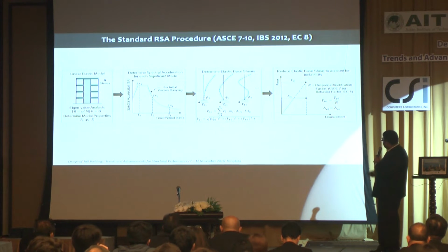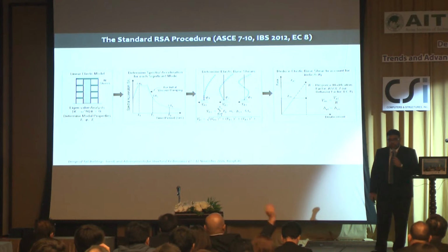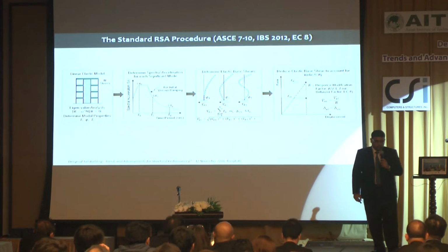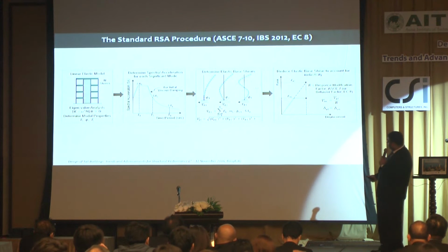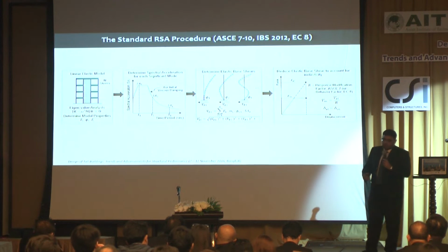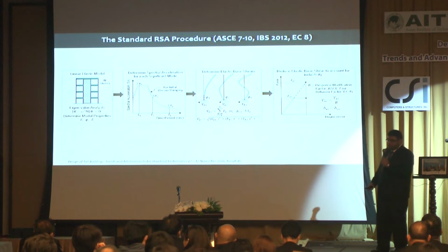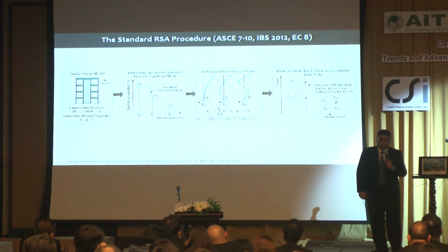At the end of that procedure, you are asked to reduce those elastic forces with a response modification factor R to come up with design forces. The displacements have to be multiplied with a displacement amplification factor.